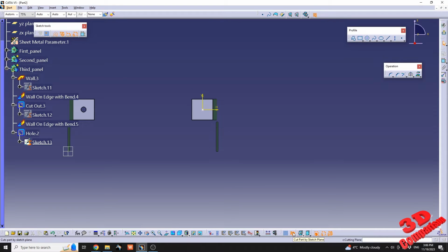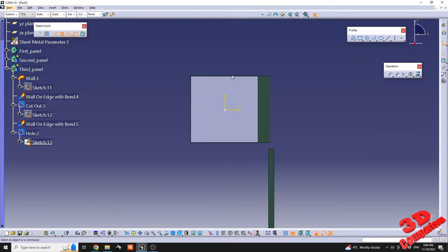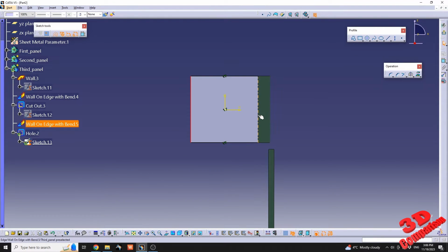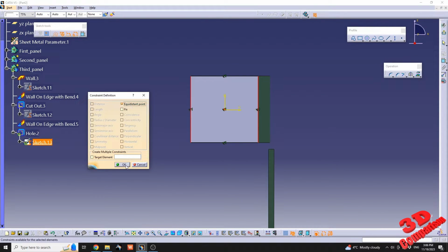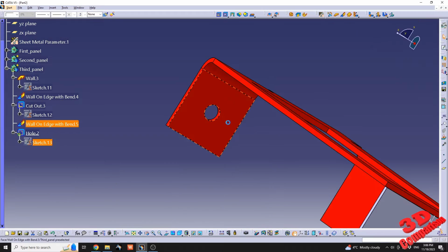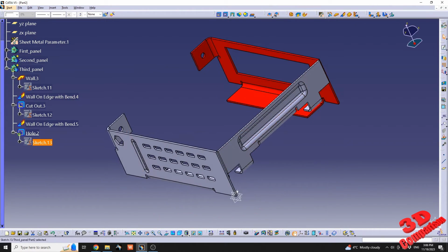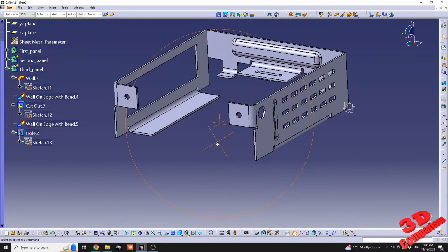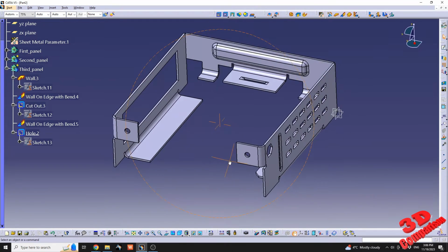This is really important, so cut part by section plane, especially when you are working with multi-bodies within the same part. It really helps to better visualize the model, because the other sections will be trimmed and you can see directly how you center the components. Okay, so let's say that this is the intended design part.